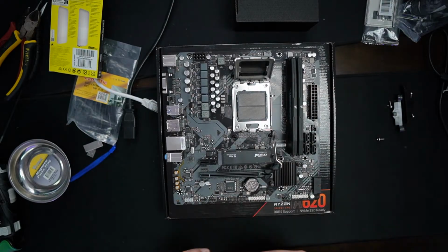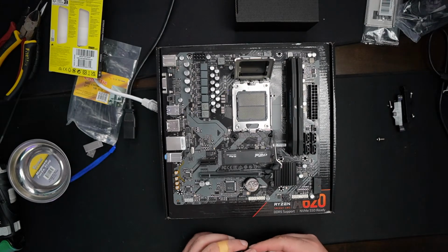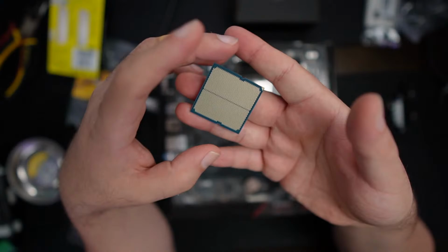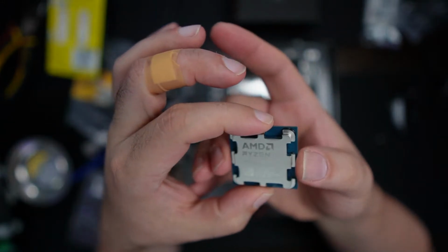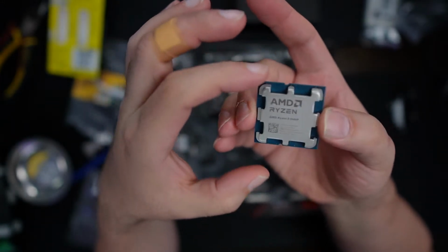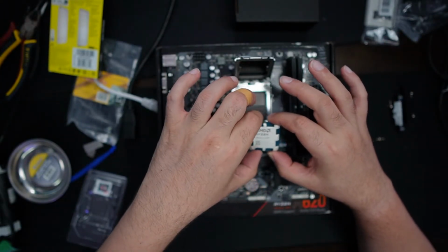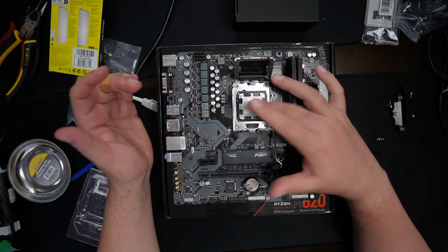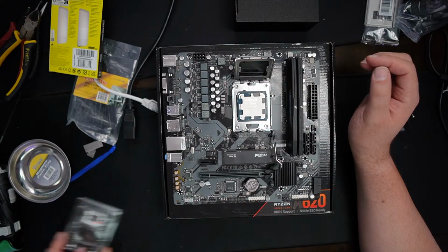Now you've got to be very careful here, because obviously when this socket is open, you could damage these pins. These pins are very, very sensitive, so be sure not to touch them. What you want to do is take the CPU from its sides. From the bottom of the CPU, you'll notice that there are a lot of pads. These pads will touch those pins and will make contact. We're going to put that downwards like this, match the arrow to the upper arrow to the left, and drop it into the socket. Not too far up, we're just going to gently put it in. I say drop, but you don't want to keep touching the socket, so that's as gentle as you can get, pretty much. Clamshell, you're done with.